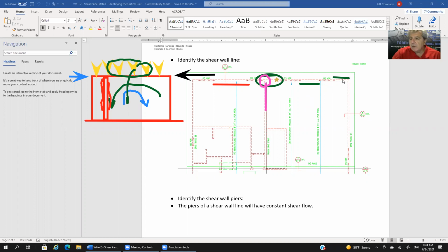Okay, now let's look at the last pier, which would be then this one here. Well, by extension of what we discussed here, the same applies here. And more so, right? Because one, this wall is at the very end, so it's not even moved in a little bit. It's holding down the very end of the pier. And the wall is an exterior wall. So if the wall is an exterior wall, it's probably going to weigh even more than an interior wall. All right.